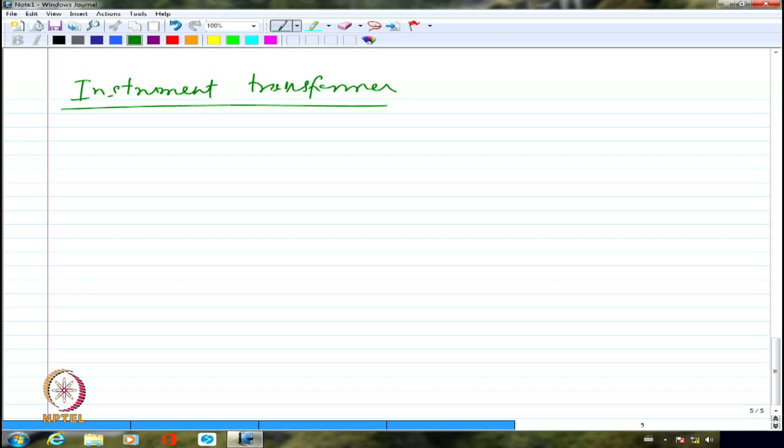Then that will be compared with a reference which is corresponding to 27 degree, that will also be probably a voltage signal. So I'll compare the two. If the temperature has not reached 27 as yet, it is at 30 degrees, then probably I'll have to turn on the compressor within the air conditioning system for quite a long time. So that compressor is going to be on for maybe as long as the coolant is compressed and then it is expanded and then it goes through the heat exchanger and overall temperature comes down to 27 degrees. This is going to take place until the temperature reaches 27. After it reaches 27 also, continuously it is going to compare it with the actual reference temperature. So if the compressor is off for too long, then again you might have to start the cooling cycle.